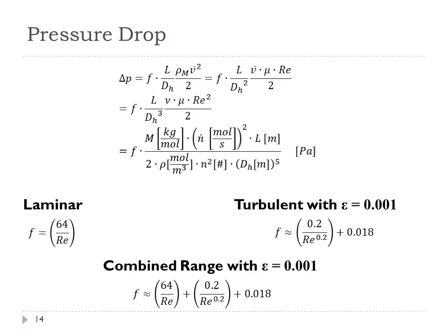The pressure drop is going to be equal to the friction factor times the length divided by the hydraulic diameter, multiplied by the mass density times the velocity squared over 2. So the way to think about this is that pressure drop increases with friction, increases with length, increases with velocity, and is going to decrease as you increase the hydraulic diameter.